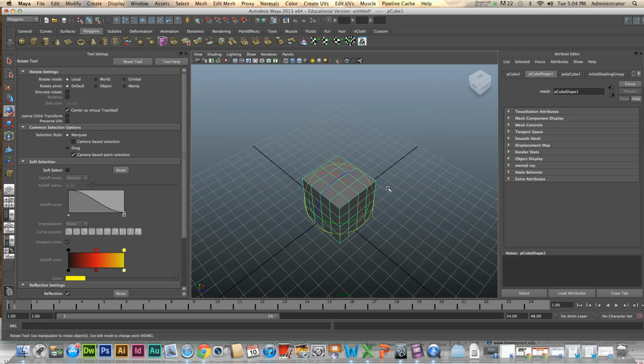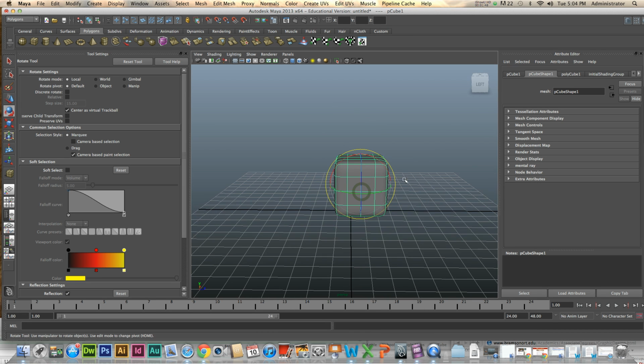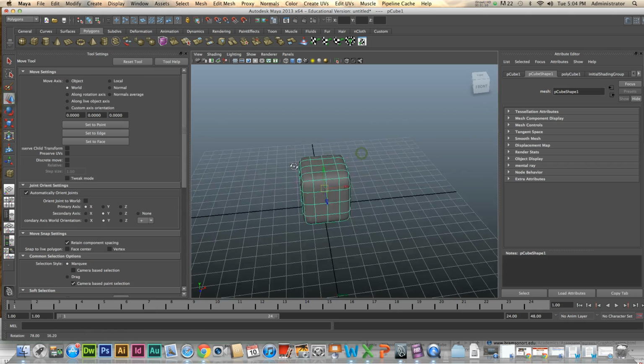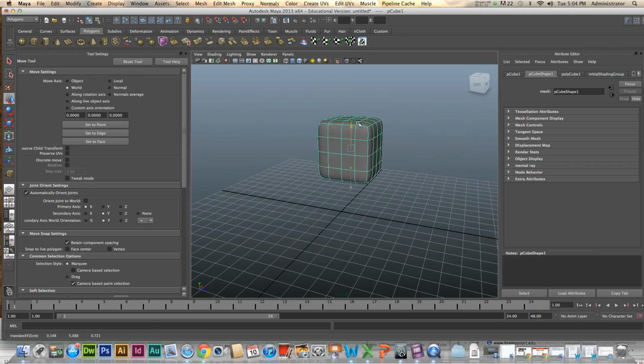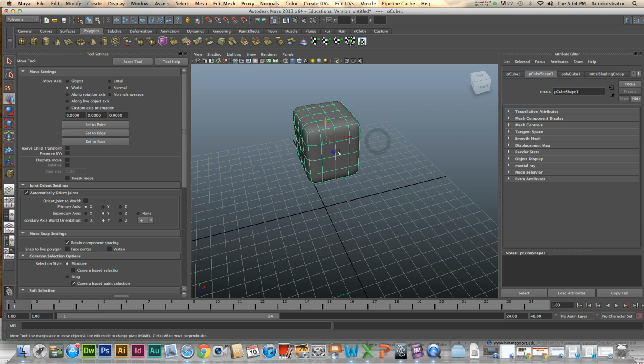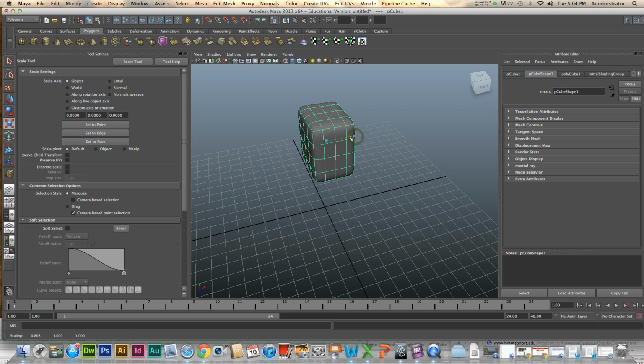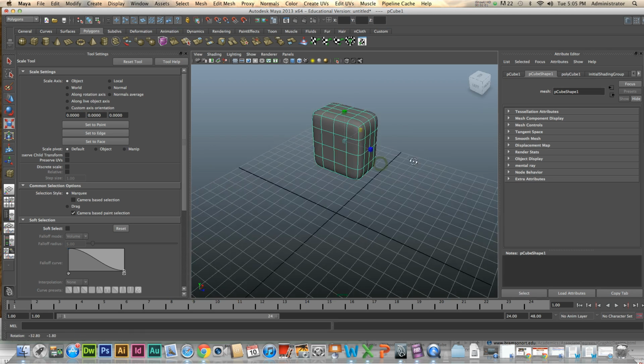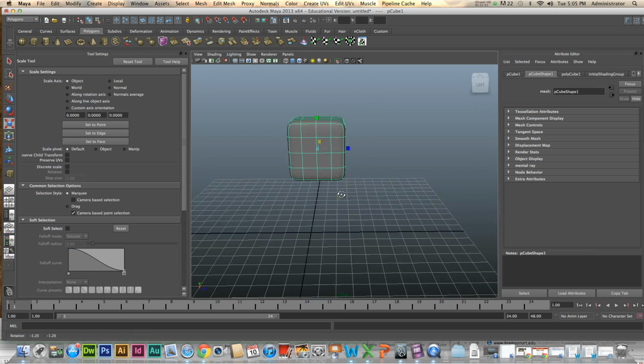Now for those of you not familiar, as a refresher, you can press 3. 3 will soften those edges. And in addition to that, if I want to create a robot out of Maya primitives, what I can do is I can press R and flatten that shape as well. Okay, so once we have this cube, this will be the torso.